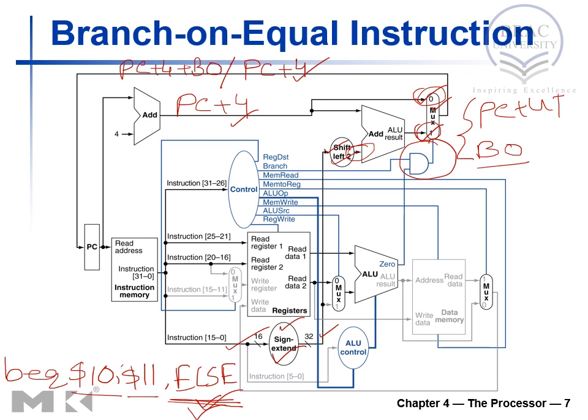Also, as I said previously, the data memory part is inactive here, which means for memory write, there will be no enable signal. Memory to register, there is no write back, so you will have no signal here. Memory read, there is no memory read operation taking place, so there will be no signal in this link, and no signal in this link.